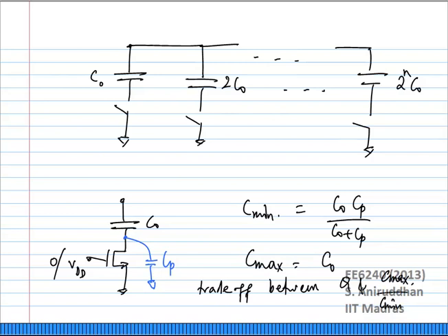And you are going to get an optimum value, an optimum trade-off between the Q of the capacitor bank versus the Cmax by Cmin, the tuning range offered by the capacitor bank. Okay? And remember, these things are fraught with a lot of issues. The minute you do this, you need to make sure you have full frequency coverage, right?